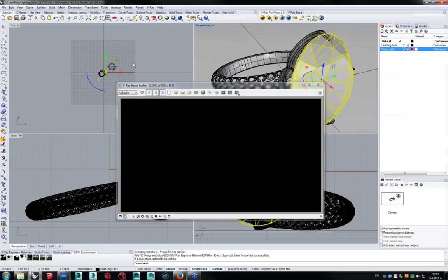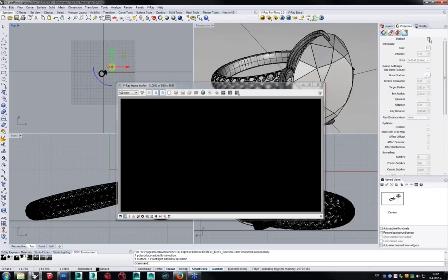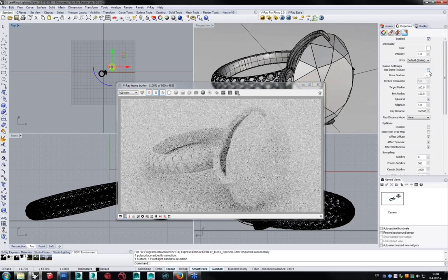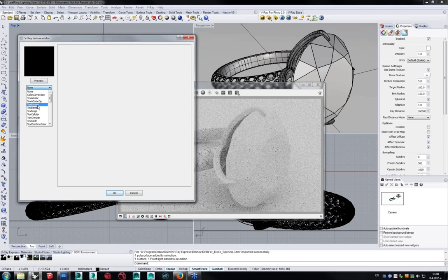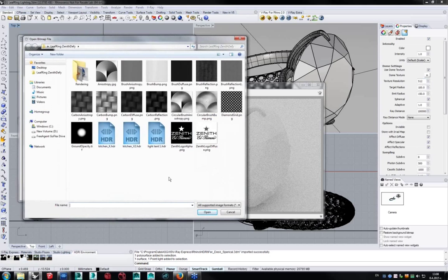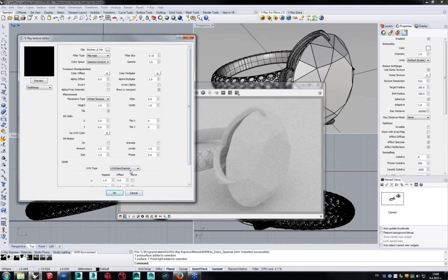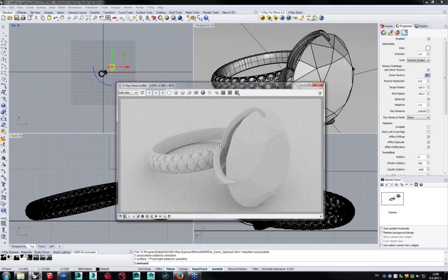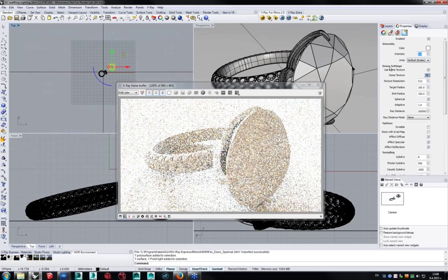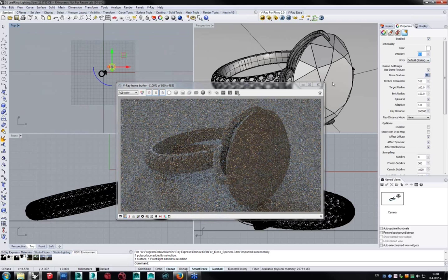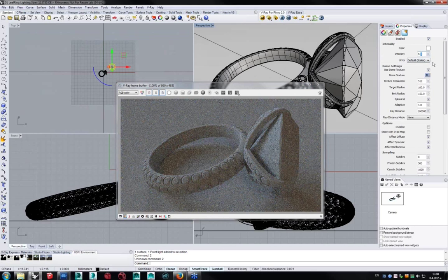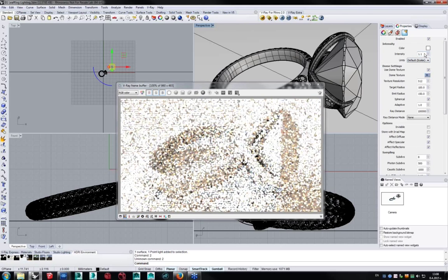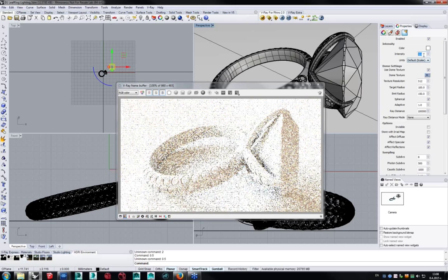So let me deactivate that and select my dome light that I was using at the beginning, and let's enable it. And if you have your own custom HDRIs, you can always just enable the texturing of the dome light and just select the proper HDRI. So currently I have a kitchen image, so let's use this one. There we go. Actually, this is quite strong for my scene, so let's lower it, and let's find a different position. As you can see, it's really giving me this natural environment as if this scene was a real one inside, let's say, a room.